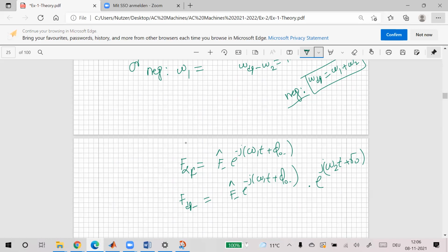I think you did something with the Clarke transformation for negative sequence. If you want to get the negative sequence value as a DC in DQ frame, then you can simply multiply with e power plus j omega. So I wrote here FDQ minus, be careful, because here we want to get the negative sequence DQ value as positive. Everything is possible, it's just mathematics. You do whatever you want for your purpose.